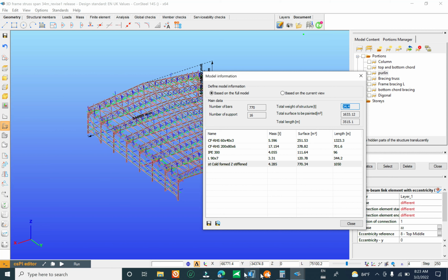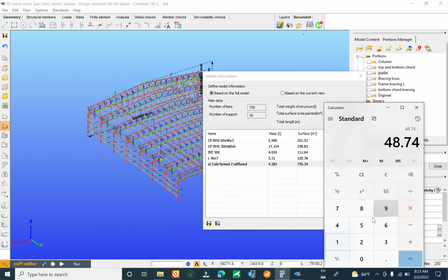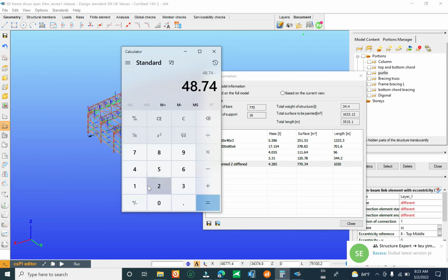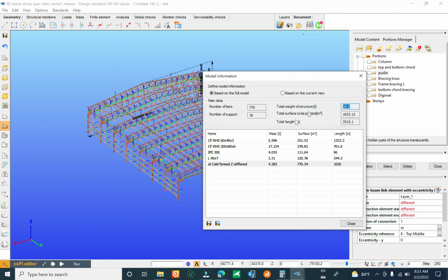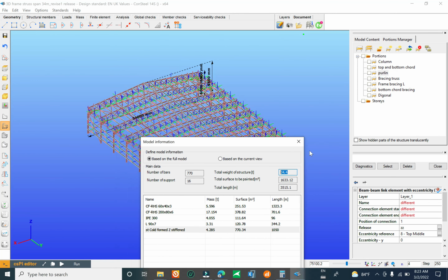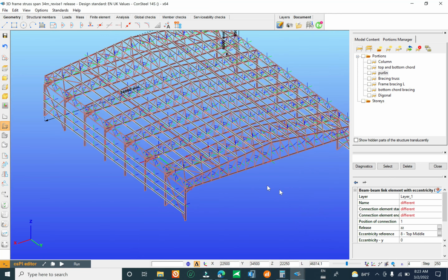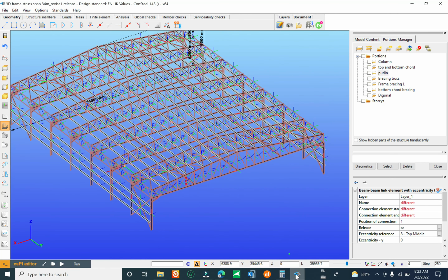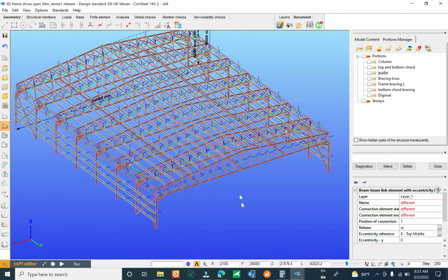You will ask why it's different between the truss design and the design for the single portal frame with hot roll section. It is the vertical deflection. The truss is good in vertical deflection, but for the column, it has a smaller section than the single portal frame with hot roll section, so we have much more horizontal deflection.